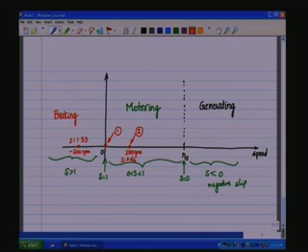And the fourth operating condition was that the slip was negative. Somewhere here we had 2000 RPM, and we had the synchronous speed of 1500 RPM, and this was case 3, and this is case 4, and the slip here was negative, minus 0.33.